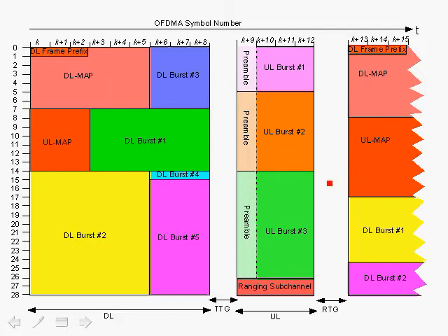After the subscriber stations send their data back to the base station, there's a RTG, which is the receive to transmit transition gap, in which the subscribers then switch over to receive mode, and of course the base station switches over to transmit mode. I'll explain the color codes in a minute.